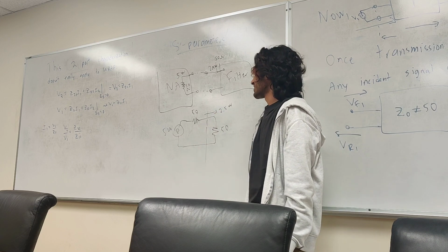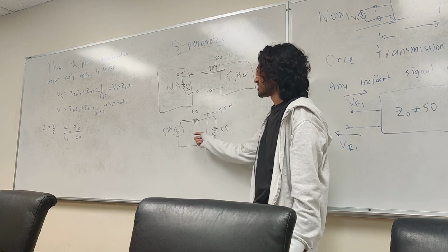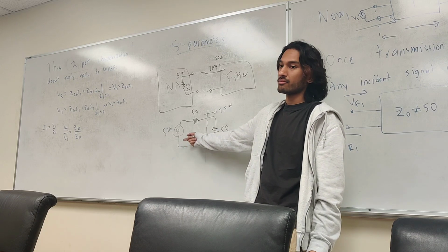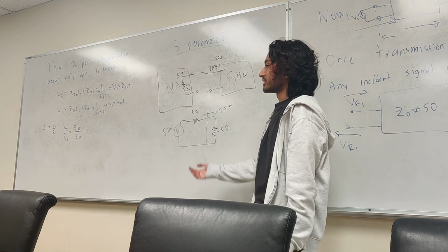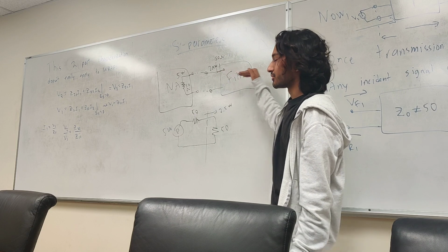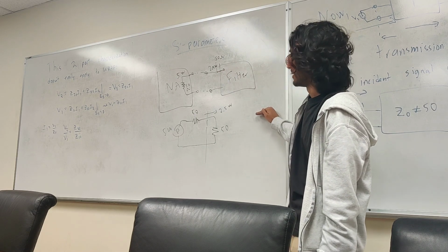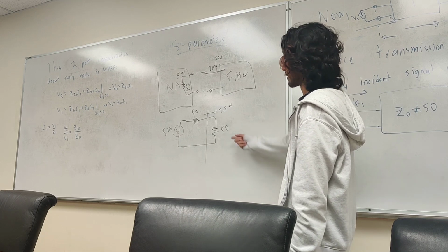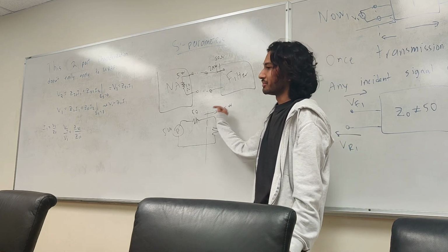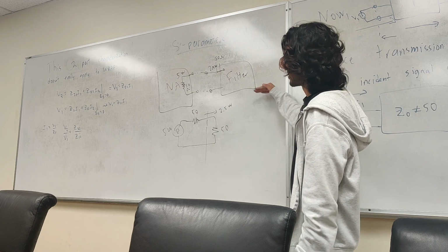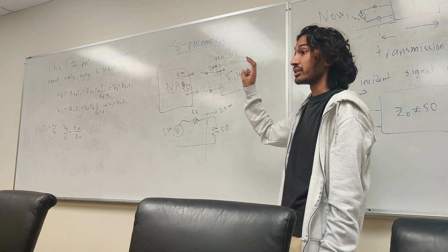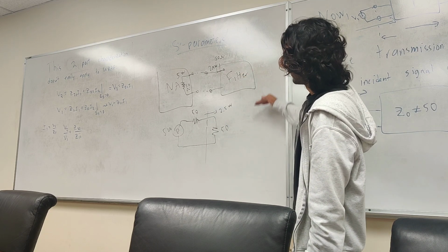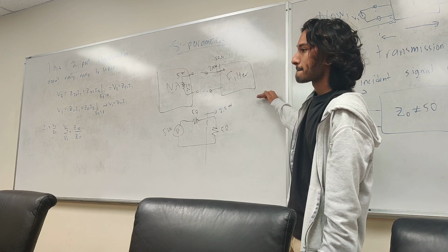What the Nano VNA does is it says, okay, I'm always going to expect 2.5 watts back, half of my input power, and it's going to calibrate itself for that. So it's going to make 2.5 watts normalize down to 0. And that way any other discrepancies it gets, so this is like 50, or this is like 75, or this is like 1, whatever power comes back is going to be different than 2.5. Then it's going to compare that to its new 0 reference and figure out where it is.